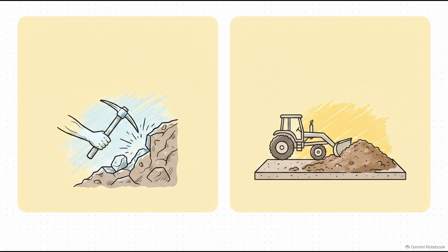Now, this station data feeds directly into software algorithms to manage two foundational states, cut and fill. Cut refers to excavation, basically areas where the natural terrain is too high and a certain volume of earth has to be removed. Fill, as you might guess, is the exact opposite. These are valleys or dips where material needs to be brought in and compacted down to reach the desired road elevation.